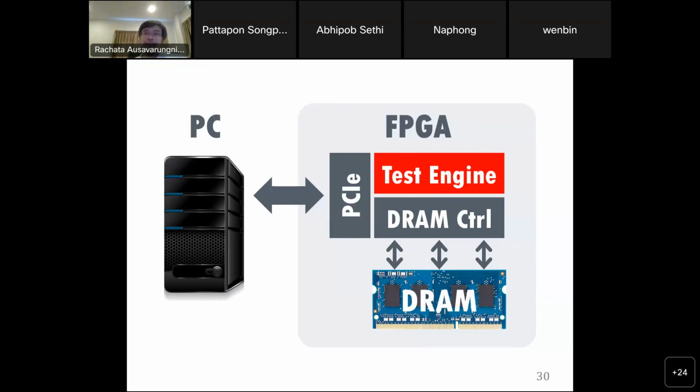In the meantime, we discovered another security bug on DRAM, the first time in the world this was discovered. It's called Row Hammer, where you write a lot of things to DRAM and it flips some neighbor's value. So you run a program normally, and you cause bit flips in someone else's program. We actually showed that this can happen. Then there was a patch from many companies, including Apple, for this bug that he discovered.